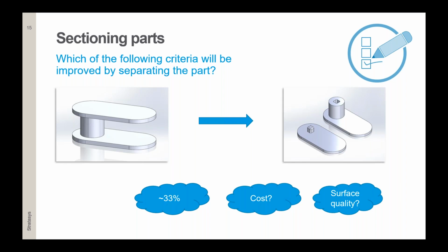For the second part, it is roughly 60 euros just for the material, without considering any time. And it translates to 20%. Regarding the surface quality, because we are again looking at this orientation, I wouldn't say that it would change much. When printing like this, we would have a top quality a little bit better, and the surface quality of the inner parts would be a little bit better, but it's basically a minor change.